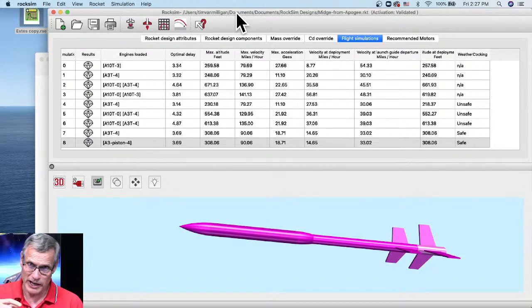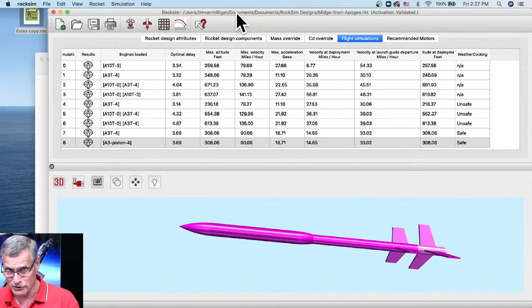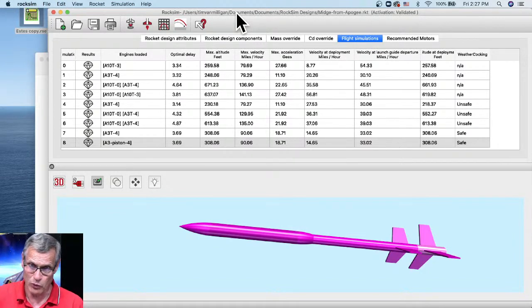So we need to create an engine, because the engine determines when the pod falls off. If you want something to fall off at 0.1 seconds in the flight, we need an engine that burns for 0.1 seconds and then falls off. But the engine can't have any weight, and it can't have any propellant weight. So this is where it gets complex.